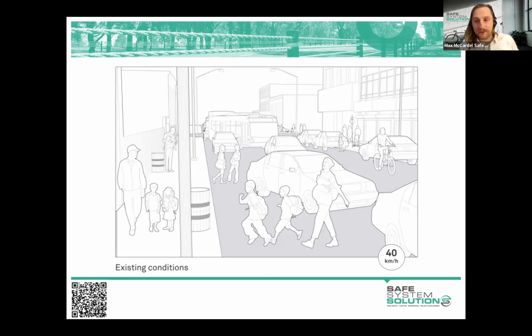So exposure, because presumably if we're making it one way, we're going to reduce the AADT, the vehicles per day through there. Ideally, you'd have some kind of traffic modeling or something like that to support that assessment. But I think, theoretically, that makes sense. If you're making this road one way, you would see reductions in traffic. So that would be exposure. But also likelihood as well, because there's just less opportunity for, for instance, head-on collisions, which would be significantly reduced because it's just a one-way environment. So I agree with that.